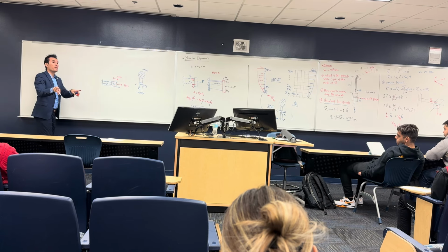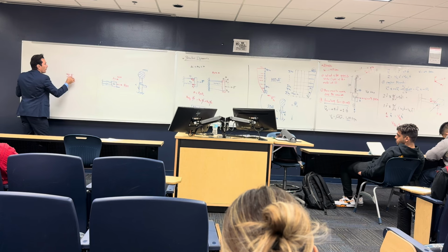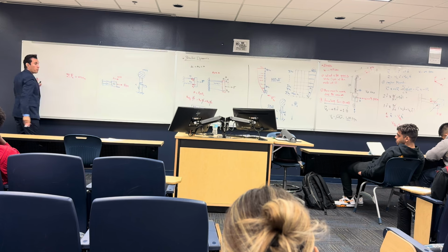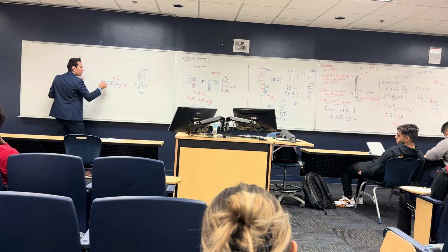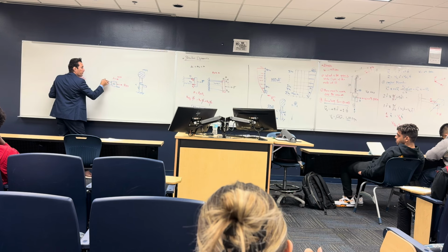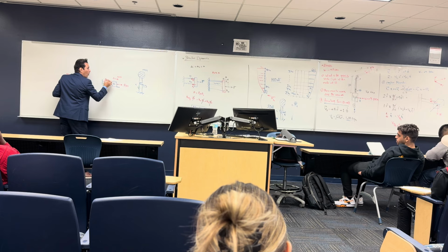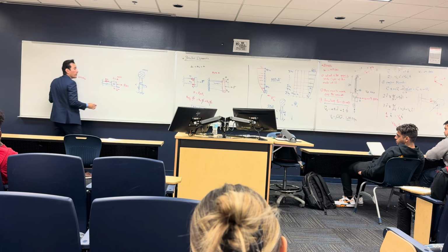It's gonna have Ma. We're gonna apply Newton's second law. So Newton's second law is the sum of the forces is equal to the mass multiplied by the acceleration, all of them in the x direction. Okay, so what are the forces that I have? I have a stiffness force, which, as we agreed before, is K multiplied by delta, or by U, let's say that this mass moved U, so I have K multiplied by U.